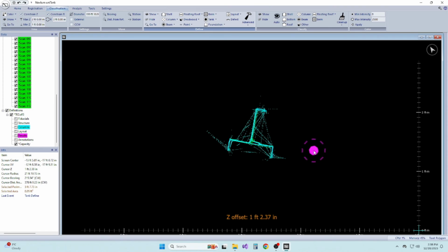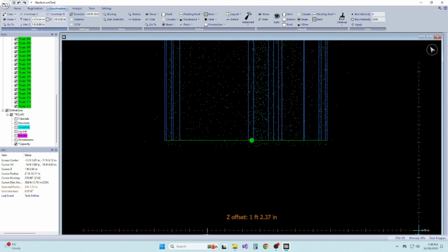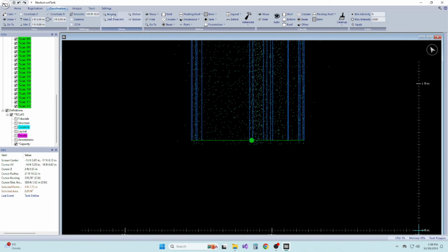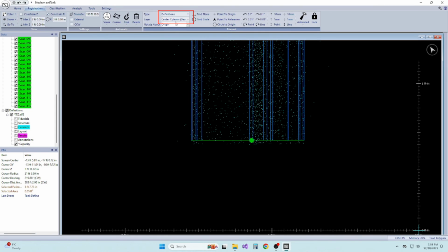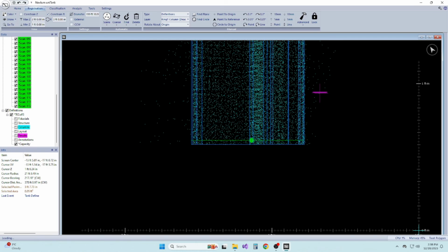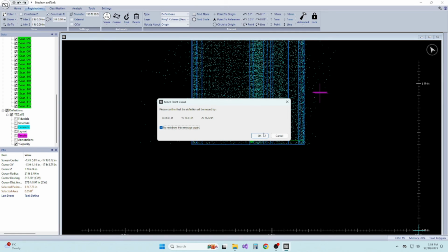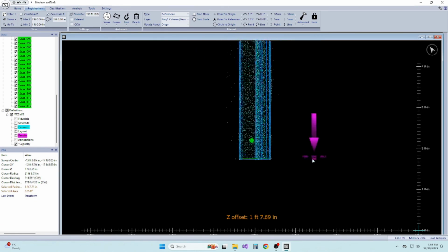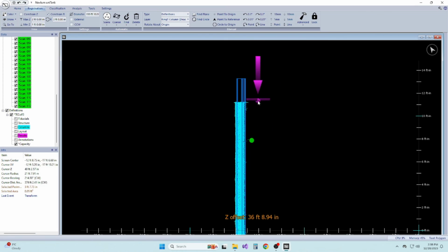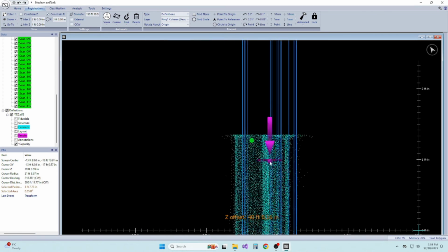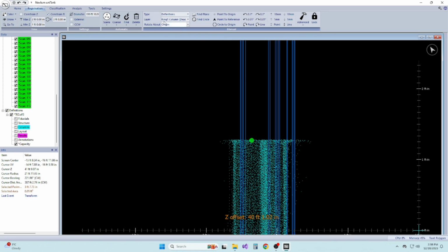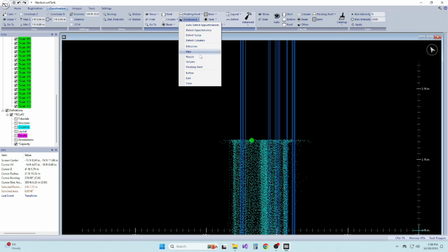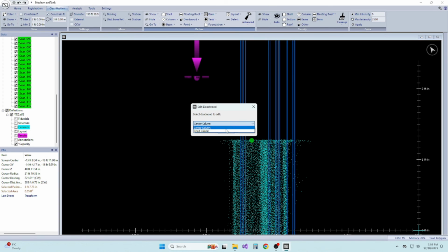If you need to, you can use the manual transform tools to move the Deadwood much like a point cloud. Just select Definition as the type and Deadwood item as the layer. Then using Ctrl-Shift-Drag, you can move or rotate the Deadwood. I modify the height so that it fits the column.